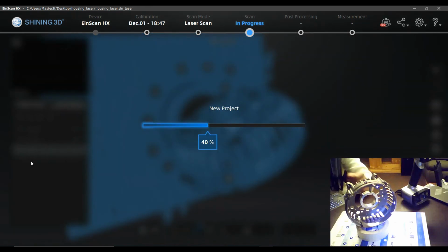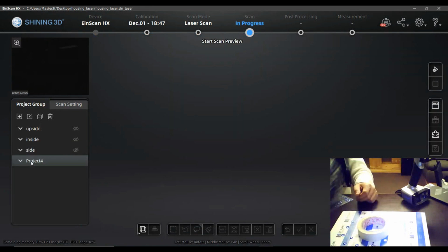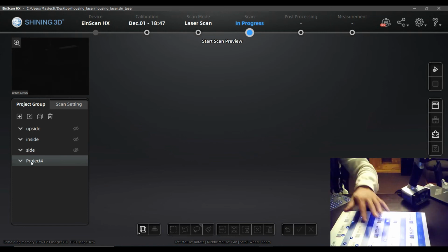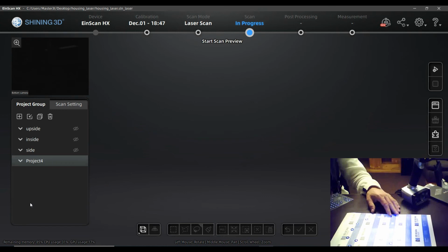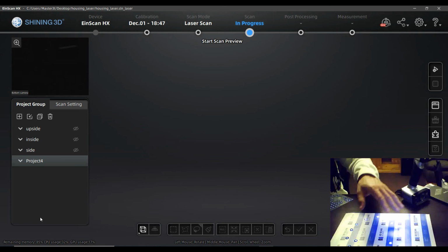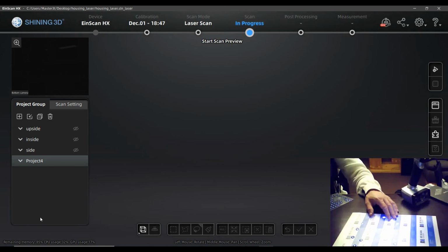And in many cases, if you are scanning, it's enough if you have some surface, or on the turntable you have markers for the scan and you don't have to apply them on the part. That as well means that you don't have to remove them. What can be really annoying if you have a complex part and you have several, I don't know, dozens of markers that you have to take off, it's really annoying.